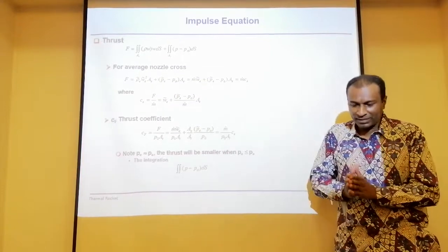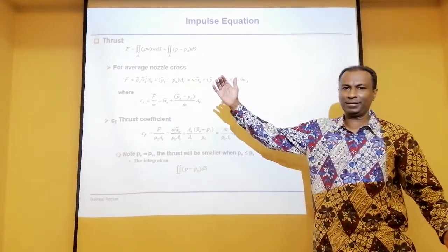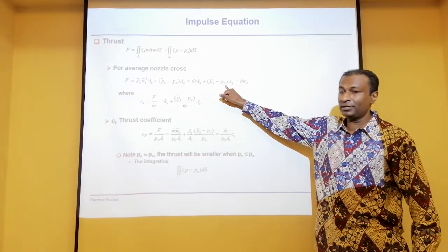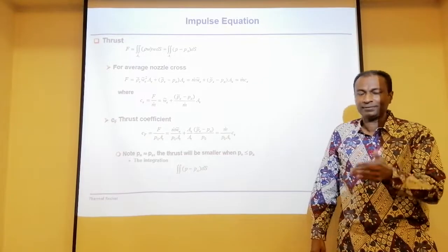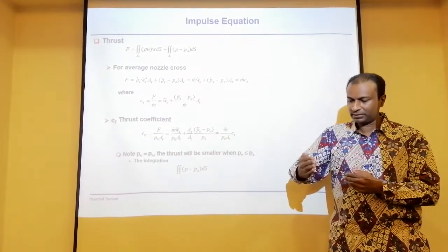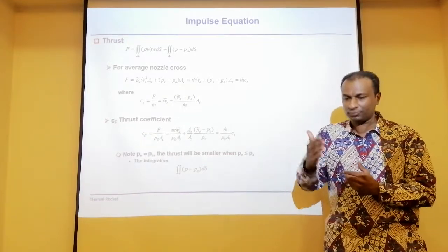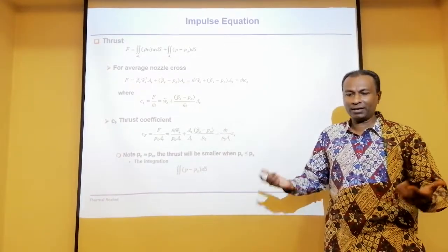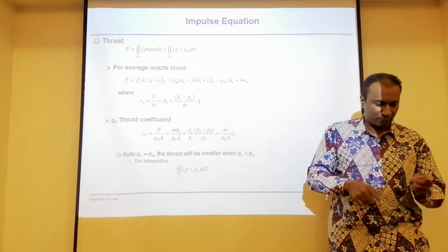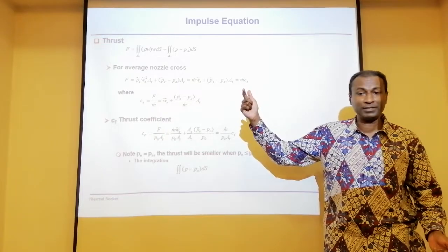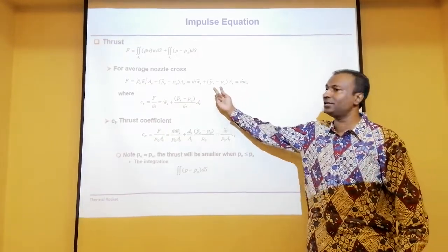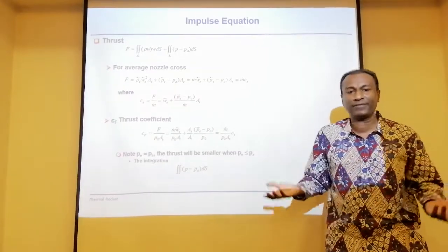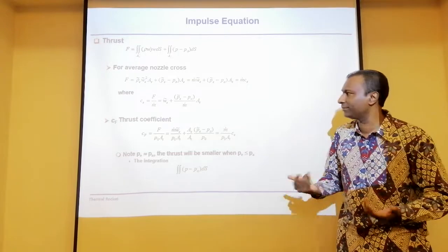Okay. Now, atmospheric pressure also changes as the flight progresses. So you can imagine this is not constant throughout the flight. Atmospheric pressure is not constant throughout the flight. Although you can produce a constant exit pressure at PE, that means at the nozzle, the delta will vary depending on the atmospheric pressure. Now, if you look at the trajectory from point A to point B, atmospheric pressure you can't control. It changes. Therefore, this keeps on changing, which means that the effective exit velocity will actually be lower, in fact, much lower.